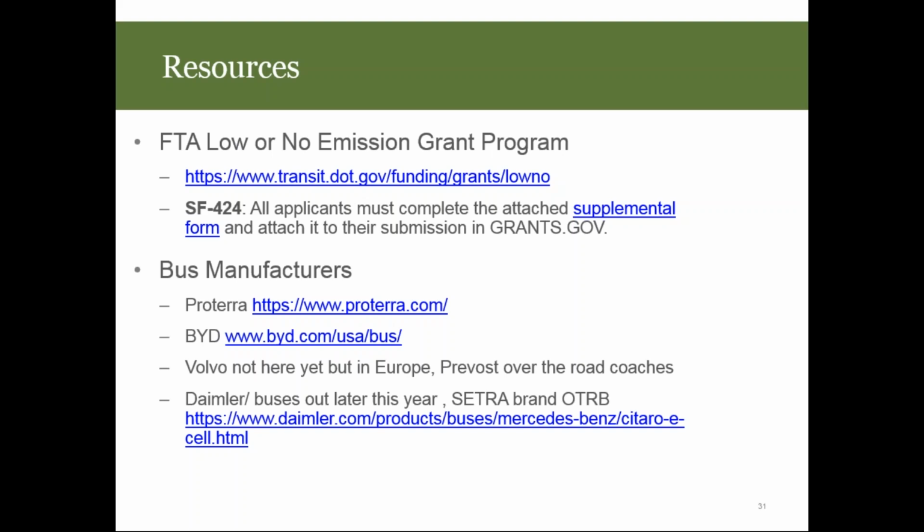One thing that I would stress is once you've picked out your area that you want to operate and you do get the buses delivered, even though you've done all your testing, we put the buses into shadow service. They had to do 180 hours, which is enough hours for 1 week, that the bus had to deliver without any problems, no issues. And once they could do 180 hours with no interruption, then we would accept the buses. So that's what we're doing with our system.